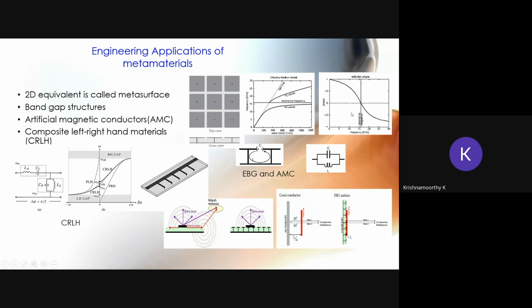So using the artificial magnetic conductor, we can use it along with the antenna, the dipole antenna here. It is shown here that we can reduce the antenna profile height. Whenever we want to avoid the back radiation from any dipole antenna, we use a metallic conductor. If we use the metallic conductor, we have to keep a gap between the antenna and the conductor of lambda by 4 to get the maximum radiation in the broadside direction.